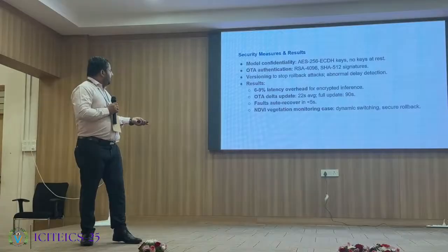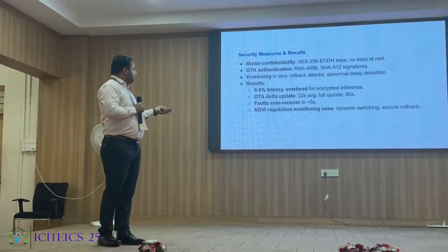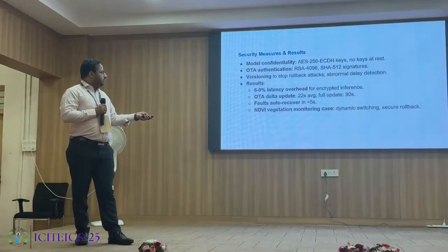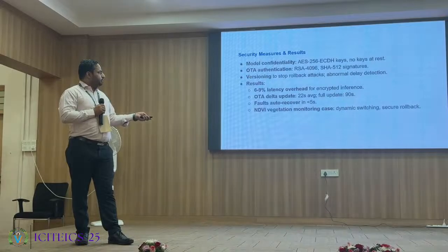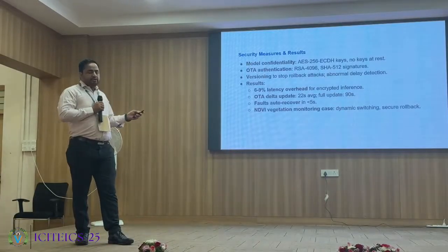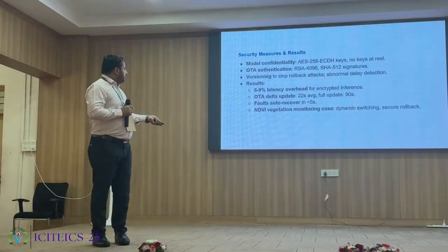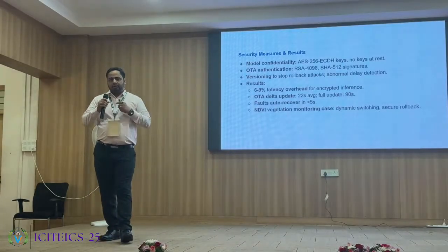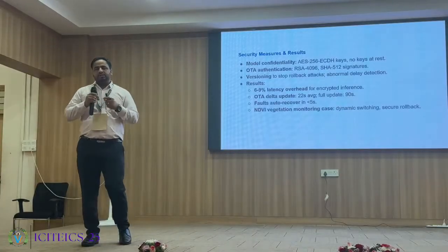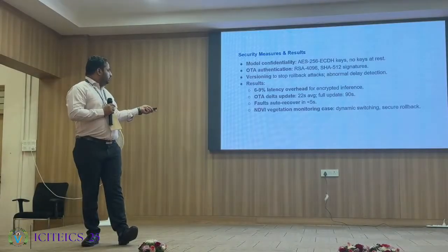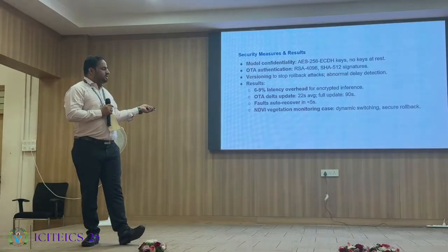And what was the outcome when we did the OTA updates? Let's suppose for a model, it is taking the full upload. Instead of this, if you just push the OTA update, which is the difference of two models, we will be taking only 22 seconds to uplink it. It will also cross-check: if the hash value of both the models is not the same, it will reject the model and the OTA update and will auto-recover in less than 5 seconds.